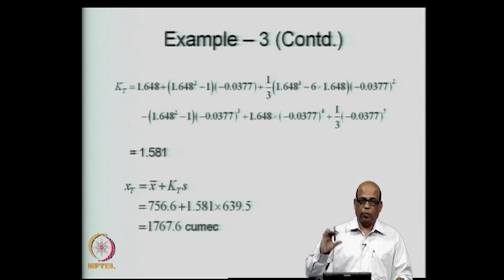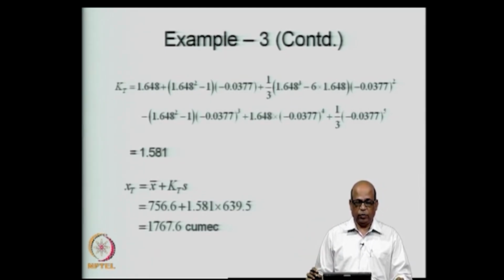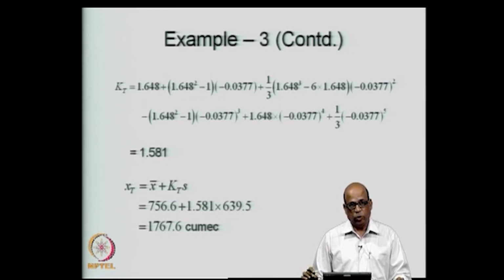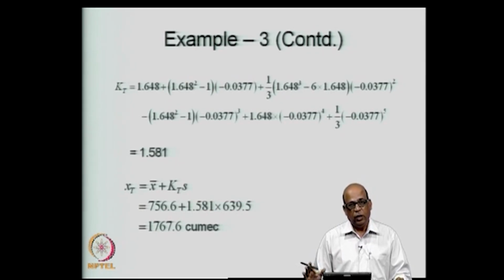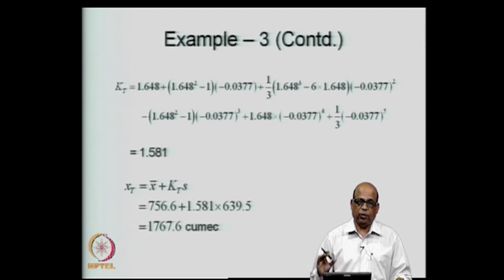in the sense of passing the discharges or some such designs, if you are talking about the spillway capacities and so on. So, the spillway capacities may not be adequately represented to actual scenarios if in fact the data follows extreme value type 1 distribution, and therefore, in the frequency analysis it is important to use the correct distribution.